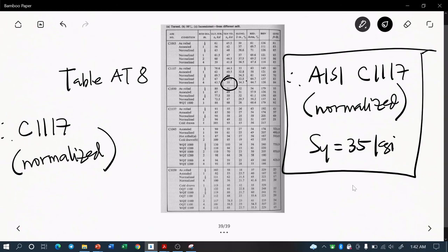So starting from the equation for the design stress, S sub S is equal to 16T over pi d cubed for a solid shaft, we obtain the design stress. Since we are given the type of loading, we were able to look up the suggested value of the design factor, and we use that in solving the S sub ys, or the equivalent yield strength in shear.